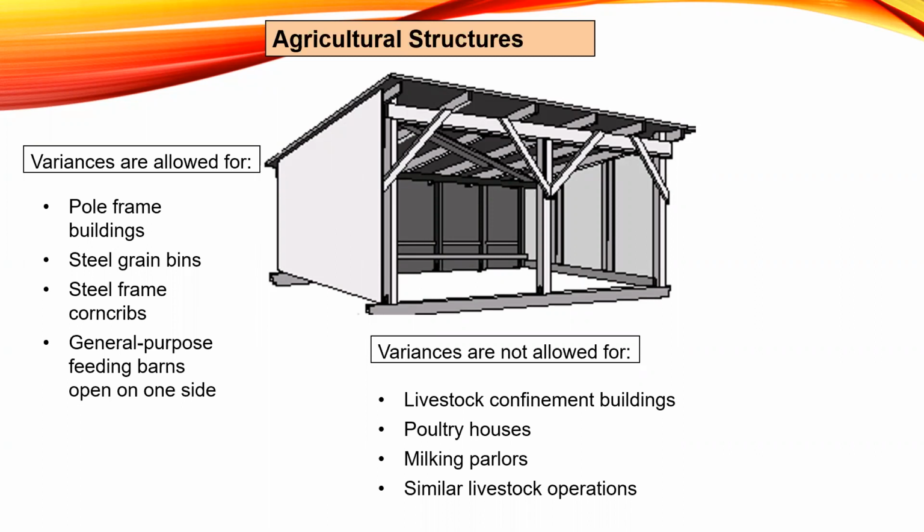And so there's no size limit on ag structures, but they do have to meet the definition. And that is, it's used solely for agricultural purposes in connection with production, harvesting, storage, drying, or raising of agricultural commodities, which could include livestock. As listed here, that still counts as an ag building, but it shouldn't be wet floodproofed. And so as long as it's low damage potential, it can be constructed at grade and wet floodproofed, no human habitation or occupancy. It's of single wall design, no permanent retail, wholesale, or manufacturing use included in the structure.